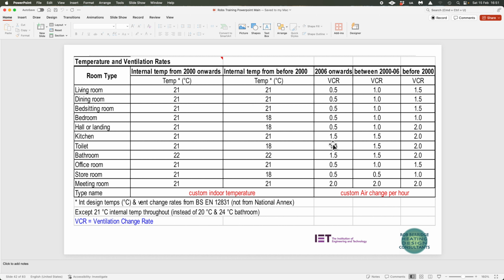So what I would always recommend that people do, and these are very, very cheap to get hold of, you can buy them online very, very easily, they're called chimney balloons. I've got one at my house, a leather one, which you basically, once the fire is out of use, poke into the chimney void, and you pump it up with a foot pump, and it seals that chimney completely. It gives you a real good seal. That keeps your air change rates right the way down.